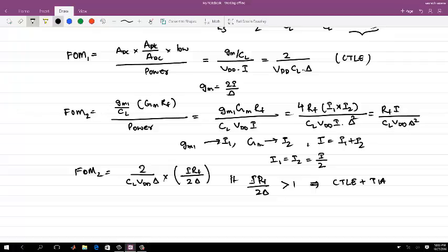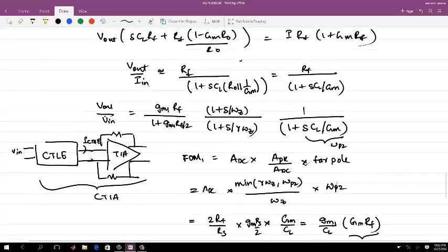And both the designs which I am considering right now are without considering the inductor in the system. So if you start increasing the bandwidth, the approach is you start using inductors here or at some other places, because then the capacitances start coming at this node, so you need to resonate those out. But that is more of an extension of this.